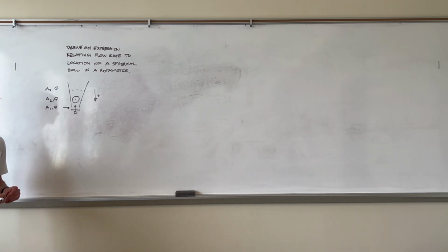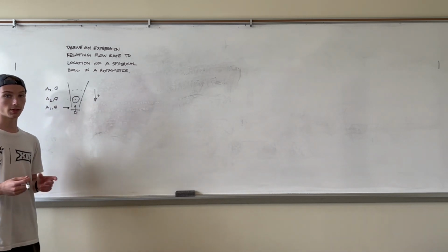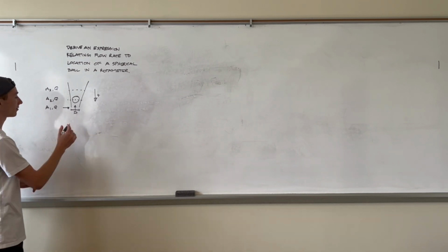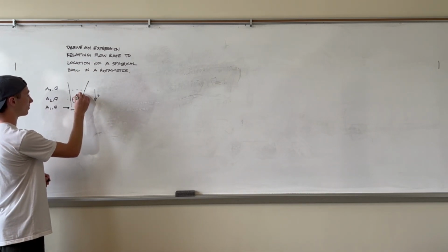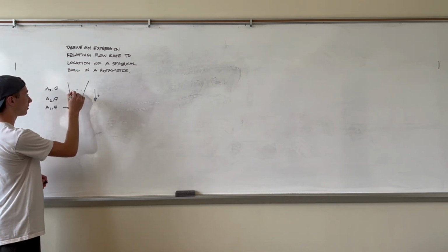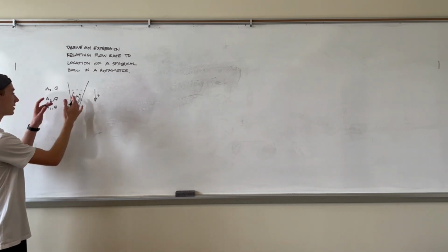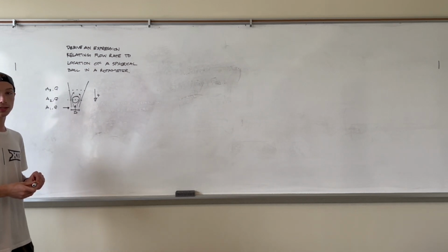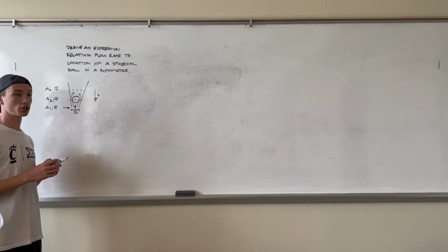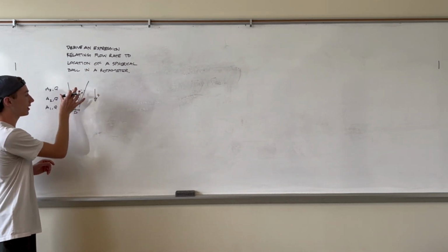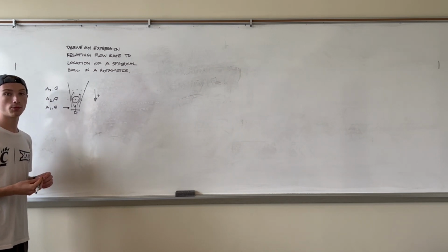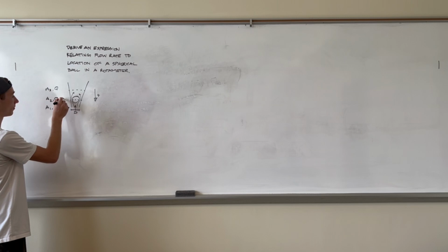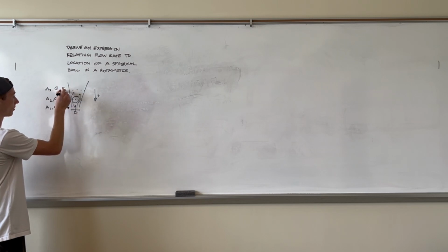A few things that we'll need to observe and also ignore during this problem: as air flows around the ball and back, the pressure will obviously change throughout these zones, but going from zone 2 to zone 3, we're going to count this as a sudden expansion of a gas around this small area, and therefore there will be no pressure recovery, from pressure 2 to pressure 3.